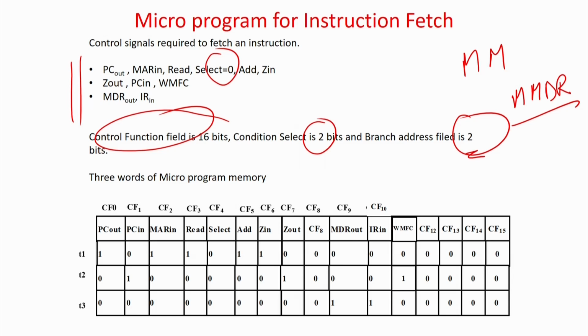So, here I am doing it as XX and control bit is 1 1. Control again I will write, that is better for us. When I said this control is 1 1, that means I am not going to look at the next address, anyway, because the control is 1 1, whatever be the input, I will just increment the value. So, I put 1 1 here and your job is done.